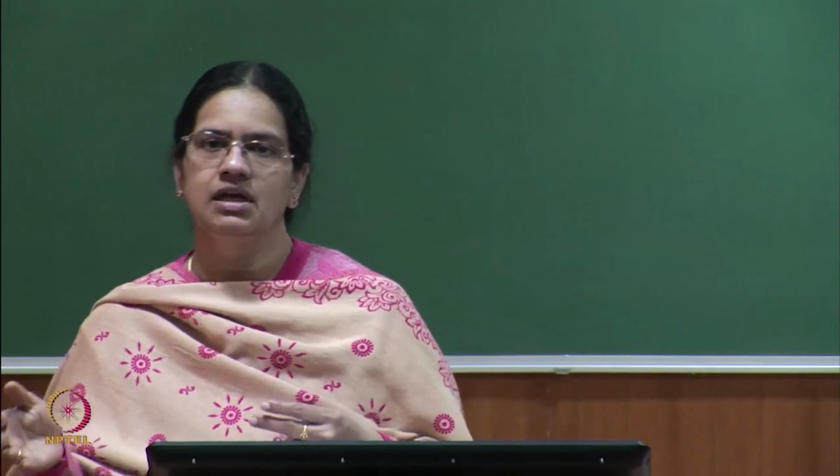Okay. Accordingly, we will have so many machinery combinations available, and based on whether it is surface excavation, confined excavation or bulk excavation, the choice of machinery also varies, and accordingly the safety precautions have to be maintained. Now, with this the major part of the lecture is over. Now, a small recap on what we have discussed.